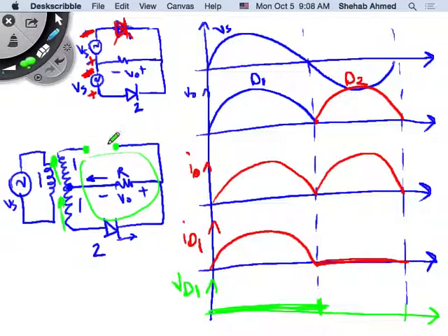So let me take this loop here. I can find the voltage across the device here, because I can take this loop, Kirchhoff voltage law around the closed loop, right? But in the negative half cycle, this diode is on, so it's just a short circuit. This diode is a short circuit, and this VS exists, and this VS exists. Your arrow, like, it's going down, but not.